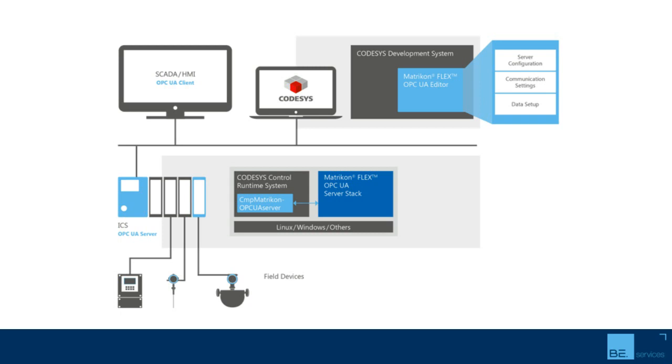So the second part that is necessary to run this application is a CODESYS control runtime system implemented on the target hardware, so typically on the PLC. This implementation is done by the vendor. They just have a commercial technical relationship with 3S. They buy the runtime system, and they install and port the runtime system either on their own or, in many cases, we help a lot of them to do that work.